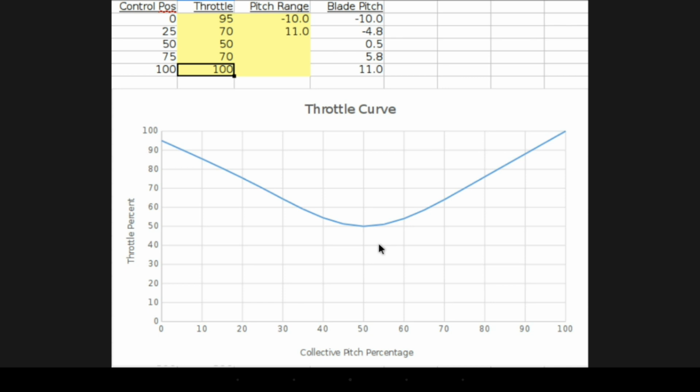Electrics are just really simple. You just set the points with an electric, and it just works. You know, there's no ranges to set or anything like that. Most helicopter ESCs look for a value from 1,000 to 2,000 PWM, and whatever you set it to, you can pretty much tweak it, and it just kind of works. Gas engine helicopter is a little bit more complicated. So we'll cover that in the second half of the video.